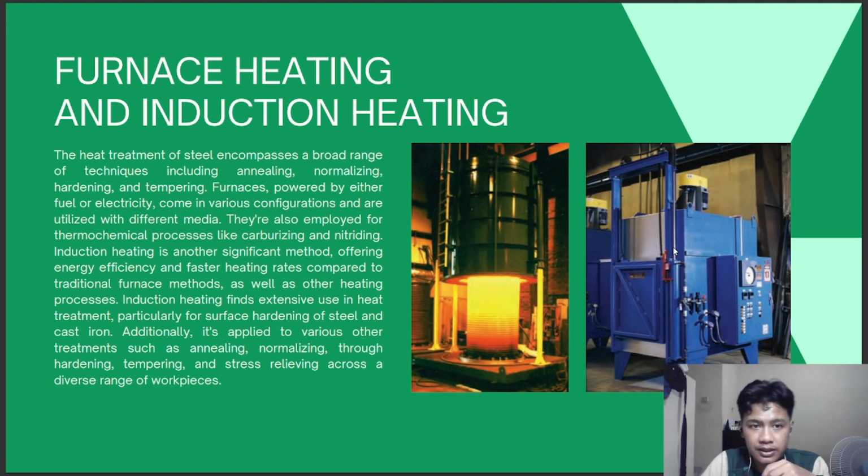Next is furnace heating and induction heating. The heat treatment of steel encompasses a broad range of techniques including annealing, normalizing, hardening, and tempering. Furnaces, powered by either fuel or electricity, come in various configurations and are utilized with different media. They are also employed for thermochemical processes like carburizing and nitriding.